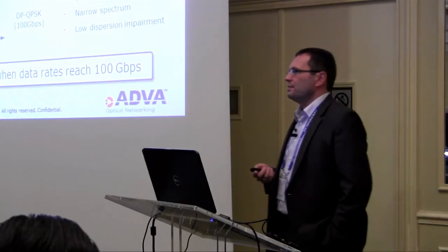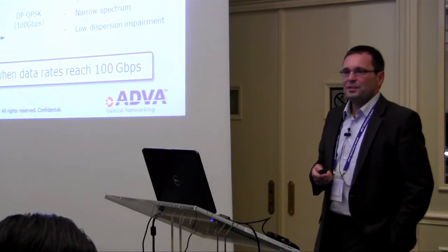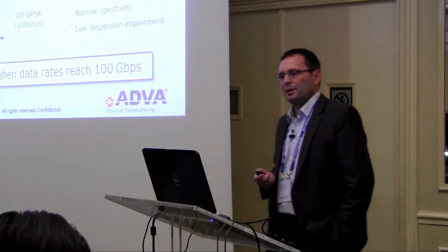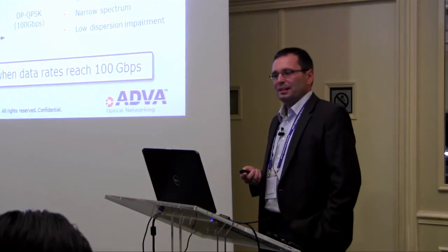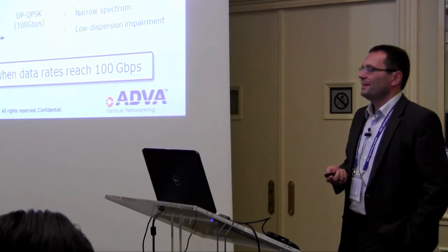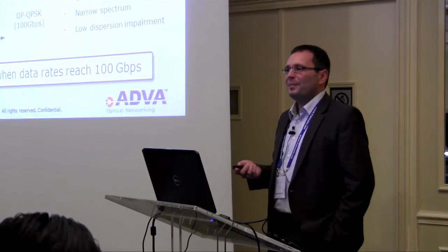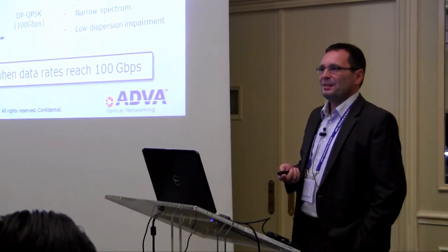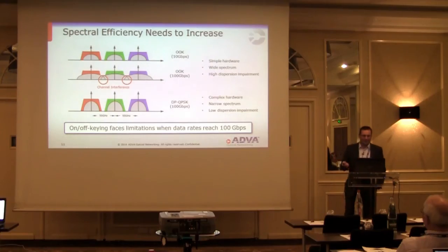Keep the 50 gigahertz grid and get 100 gigabit into a 50 gigahertz channel. So we're using something new, a new modulation format, and we want to talk today about QPSK, which suddenly makes the 100 gigabit fit into the 50 gigahertz. Sounds like a magician, sounds like a lot of magic, but it isn't. It's a lot of mathematics. It's a lot of physics, but you will understand very easily what we do there.